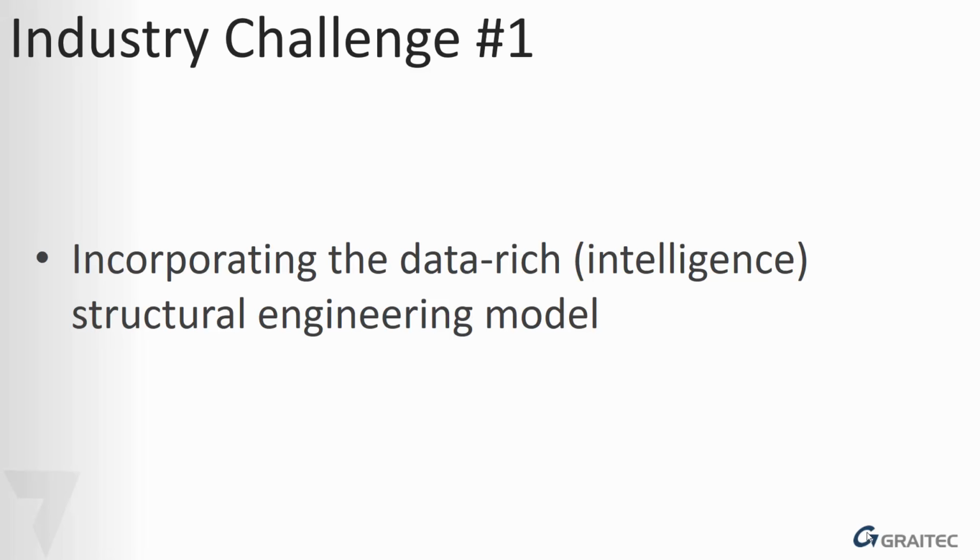So the first thing that needs to be done is the Revit model needs to be created in 3D. Sometimes this is happening before or during the engineering process. With this, we will be able to create our sections. We create column sections, foundations, and these are represented often as families in Revit. With these section definitions, we will create elevation views. From the elevation views, we'll be able to place rebar, as you can see highlighted in yellow here.